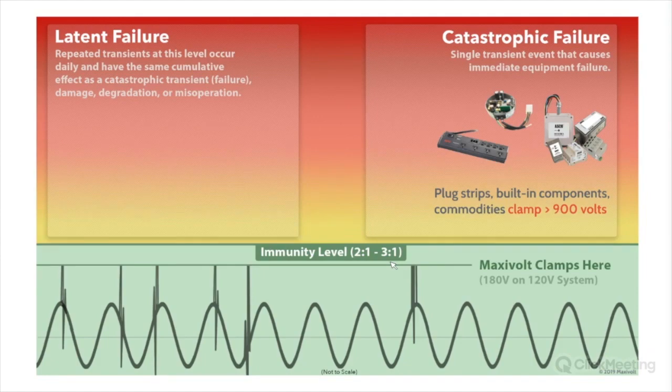which a lot of times relates to utility lightning arresters out on the pole for power distribution. Most of the time, lightning currents get on high voltage transmission lines or distribution lines. They're not really down into the equipment level. But the voltage level has a lot of fluctuations, and a lot of transients go through into the low voltage equipment, even though upstream we think we have lightning protection. We miss the actual reliability component of making sure the voltage limitation works effectively for the equipment you're trying to protect.